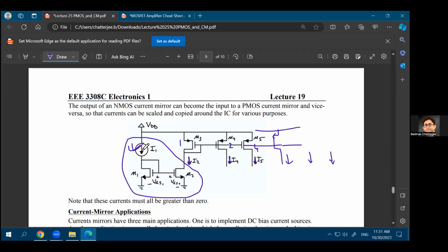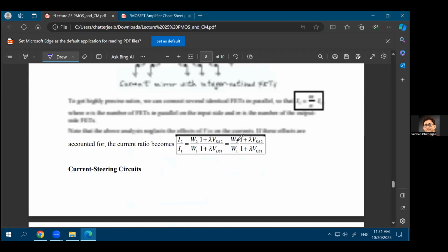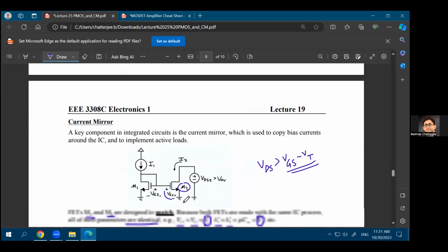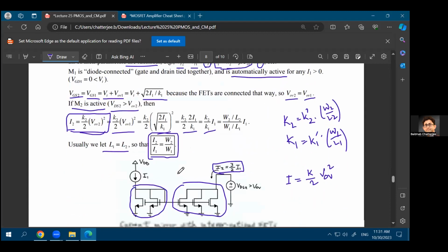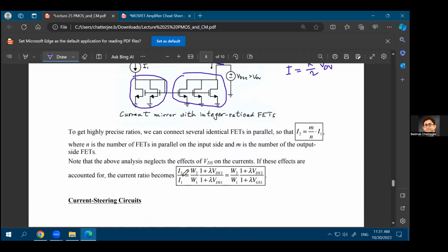The use case, yeah. Initially what we were discussing is that you want to bias transistors, right? And we said that biasing using voltage is probably not a good idea because of noise, interference, and IR drop. But biasing using currents is a better idea. Now you can have different components. Let's say you have 2 different amplifiers, 4 different filters, 3 different buffers, and you want to bias each one of them separately. Either you needed 7 or 8 different voltages from the external world, or you can have only one current from the external world and mirror that current into 7 different places to create the biasing for all the different components of your system.